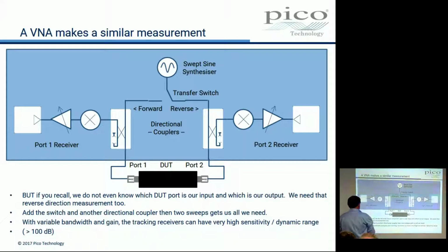There's an important thing about these receivers. When we look at this signal with a tuned receiver, we can have a very, very sensitive arrangement indeed. A radio receiver can work to very, very low signal levels and still recover the signal, because it does so by looking in quite a narrow bandwidth.